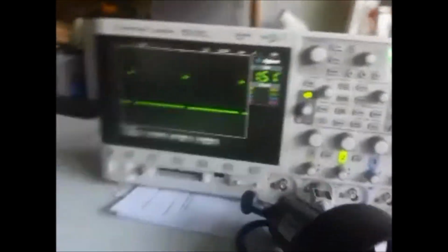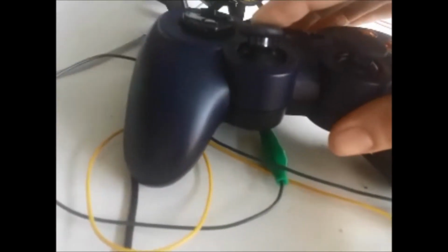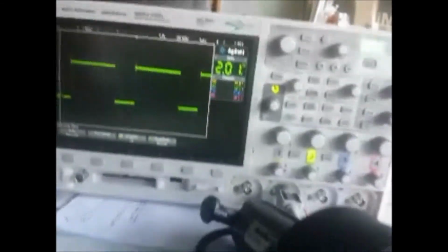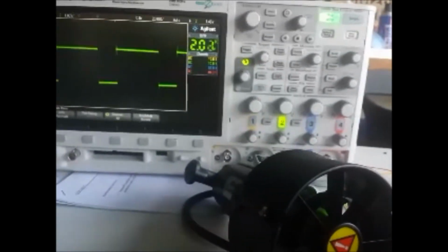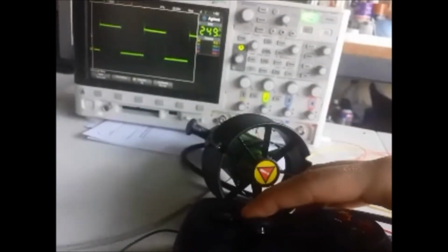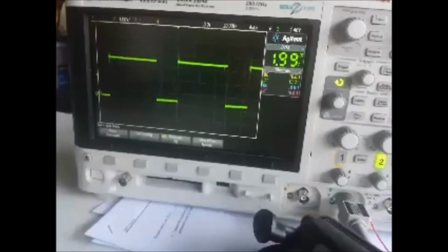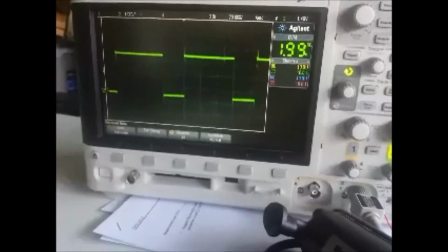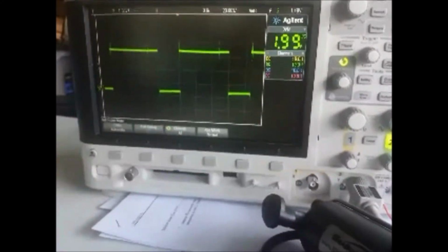I know that the maximum joystick placement I can go up to is 70% duty cycle, and I know that the microcontroller is emitting 3 volts. So you take 3 volts and multiply it by 0.7, and that should show around 2 volts, and it does. So we know that when the joystick goes up and I'm receiving the signal right here, this is right around the max. The reason it's not exactly 2.1 volts is because there's always going to be some slight deviation for error.